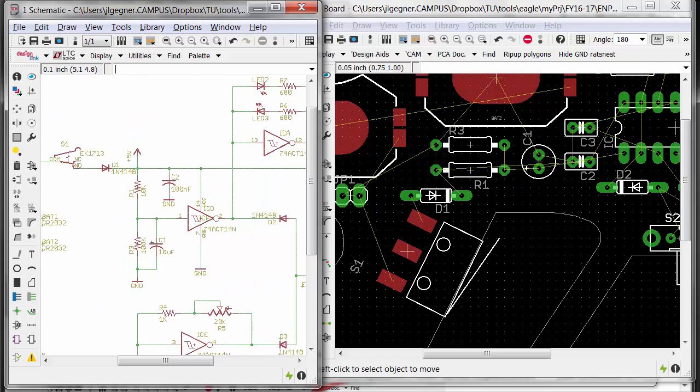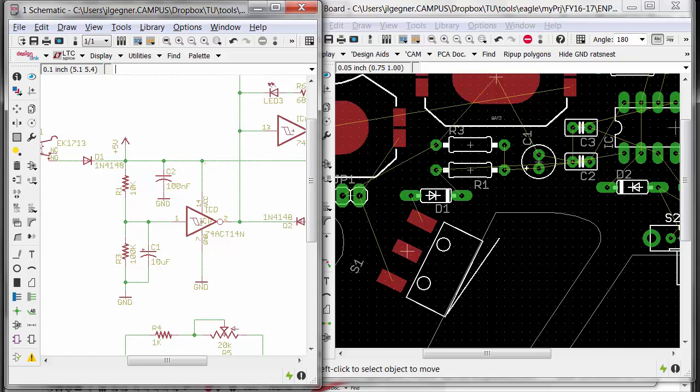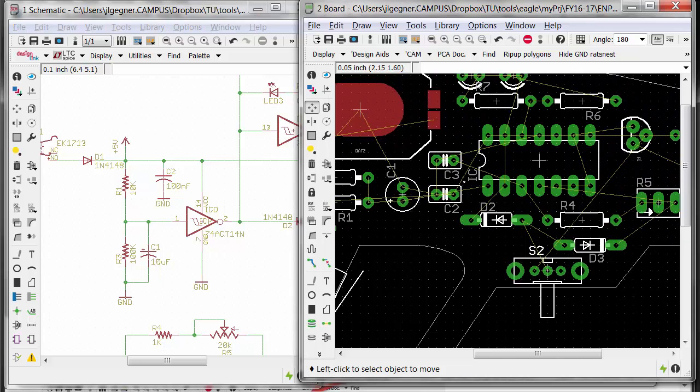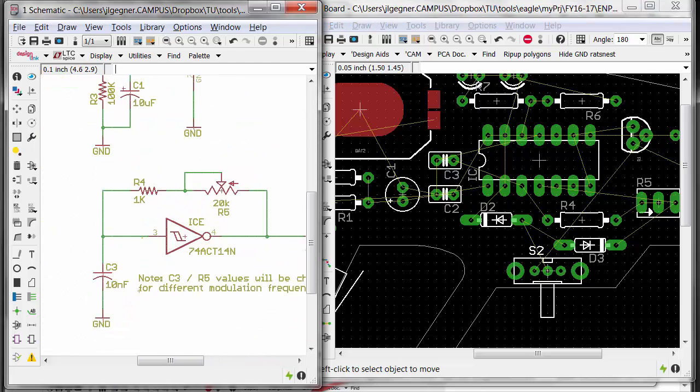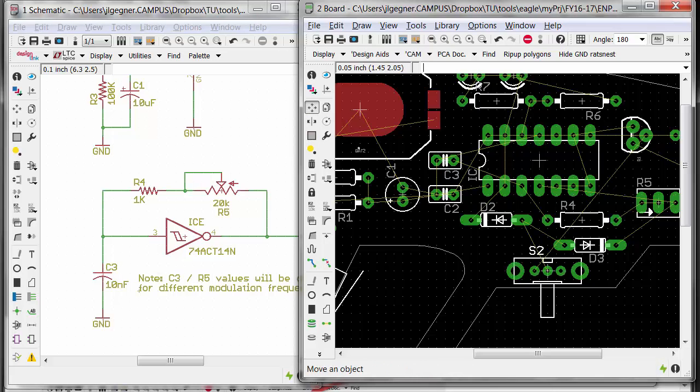When I get to the IC, because this C2 is tied between the power rail and ground, I know this is a bypass capacitor that is needed to basically provide clean voltage to the IC. So you usually want to put a bypass capacitor close to the IC. So I've placed my C2 right here. It's pretty close to it. This part of the circuit where I have the C3 at pin 3, I have placed here, not super close. I might want to switch these around, right? But you start getting an eye for where it's going to have to route.